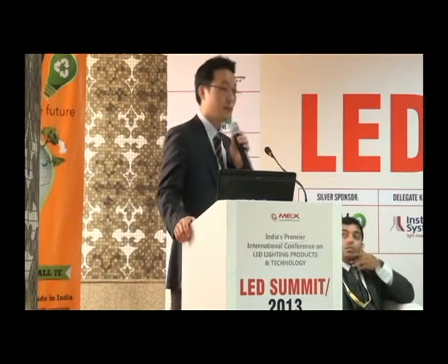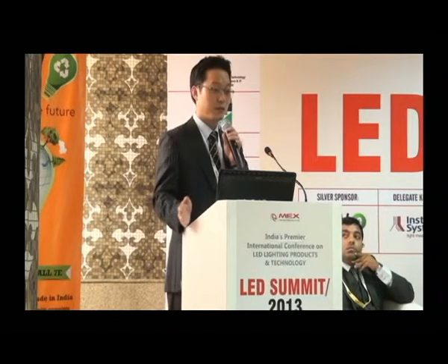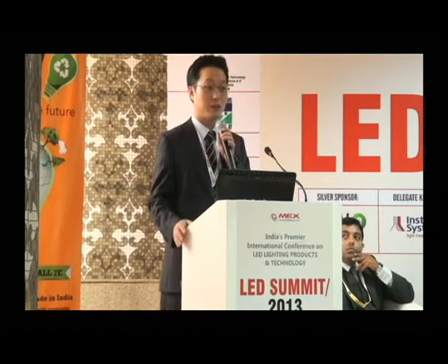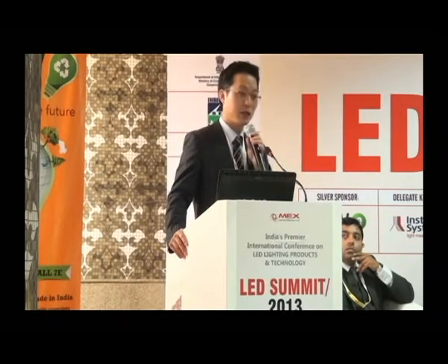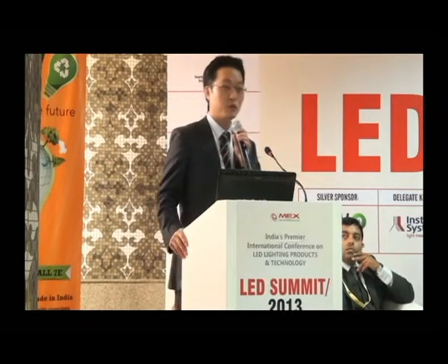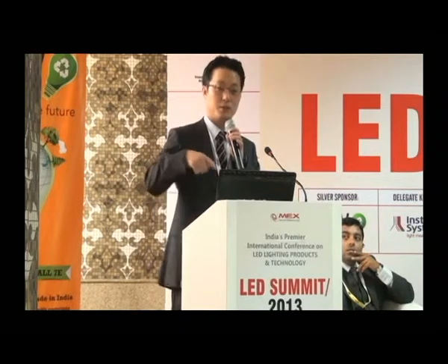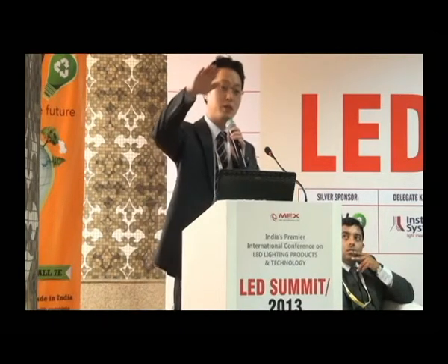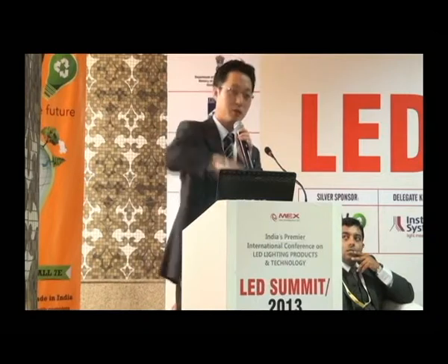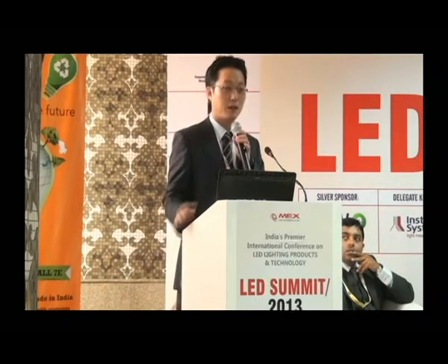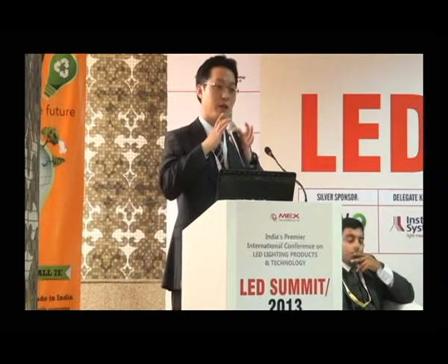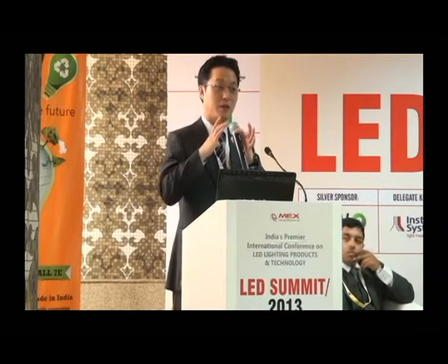In that case, because phosphor material density is around 2.5 and silicone material is lighter, just around 1.1, if you mix phosphor material, as time goes on the phosphor will go down and sediment to the bottom. In that case, you cannot make a uniform LED package.